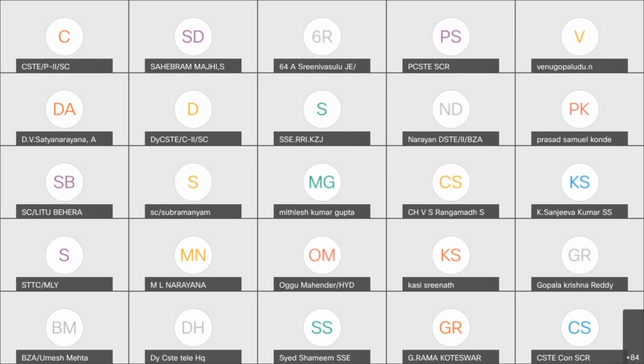So this series operation, parallel operation has now become relevant with the TWS machines. Normally, these high thrust machines draw double the current of normal 140 mm throw machines. So if there are multiple obstructions in crossovers, the power calculations we do are not holding good. Like we provided a 20 amps fuse in the IPS for point operation. Assuming there are multiple obstructions in high thrust machines at multiple locations, again these power calculations are going haywire. Do you think we should go for series operation in such cases, or we should strengthen our cables or IPS?